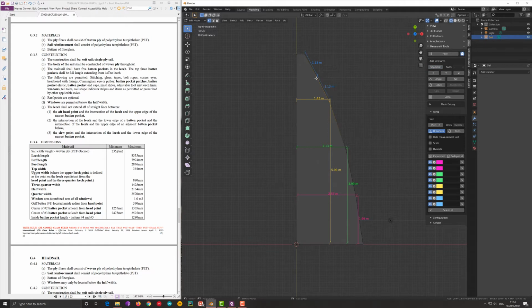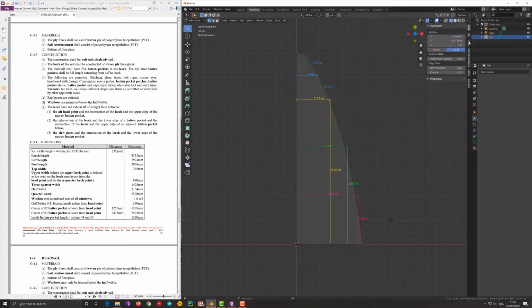Of course, since I have subdivided, the software has already divided into exactly equal pieces. So when I press X, it will show me what is the actual length, which is 89. Okay, I can select this vertex, and I see there is 0.89, which is basically almost 88, but to be sure, I just put 88 millimeter. And here I have it.